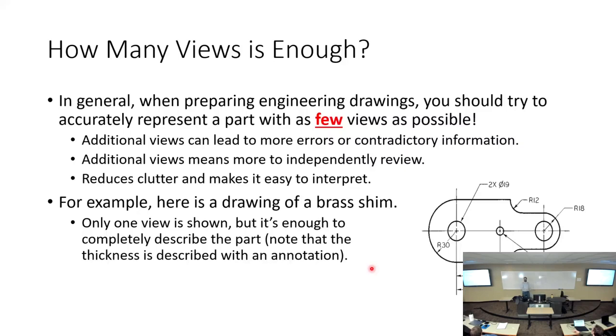I have, let's say, a metal plate, a rectangular plate, and I have a hole in that plate. Notice how the hole is not in the center. It's not in the middle. We'll say that this mark right here is where the center of the hole is. Now I'm going to ask you a somewhat basic question. How many dimensions, how many data points do you need as a fabricator to be able to fabricate this as specified? Now I propose all you need are 6 data points.